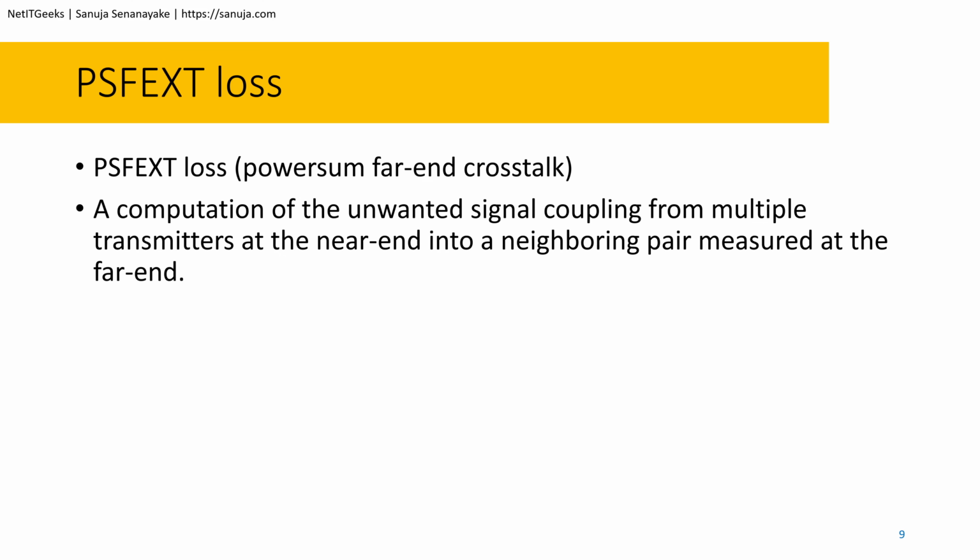But this could also be caused by improper termination, such as too much untwisting. Nicked conductors can also introduce impedance mismatches, increasing the amount of crosstalk, just like previous losses that we discussed before. Defective termination hardware can also cause issues.